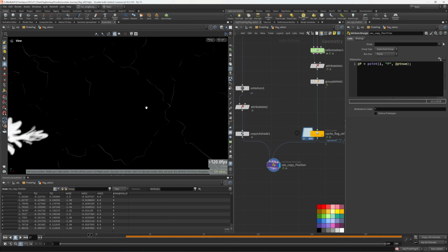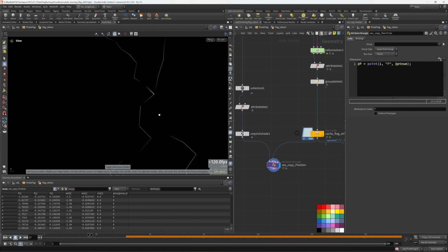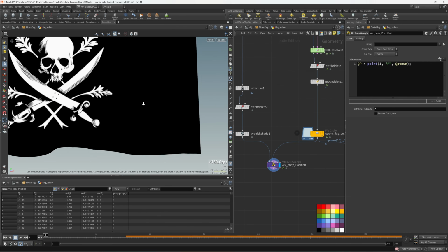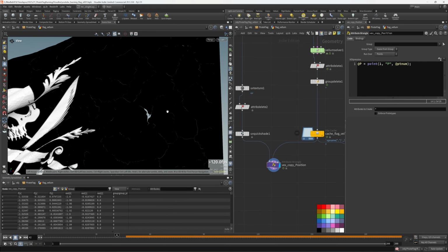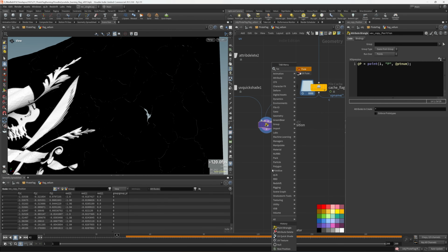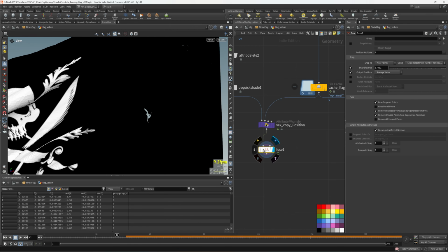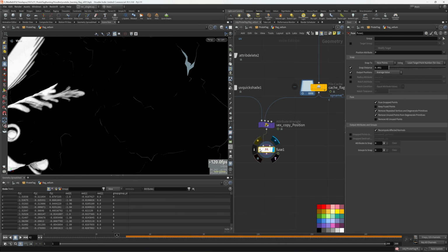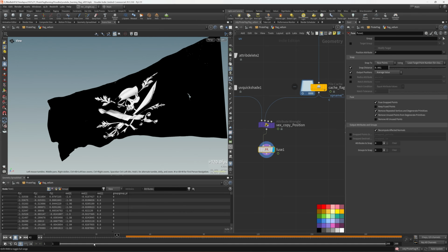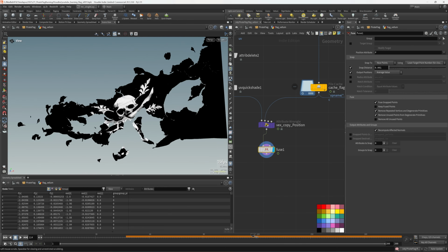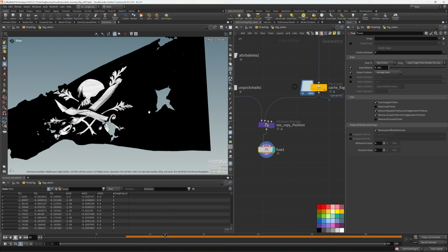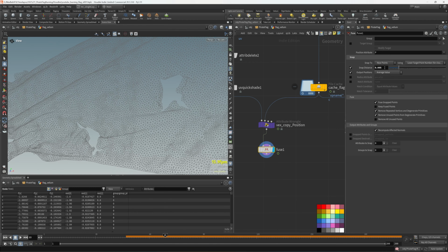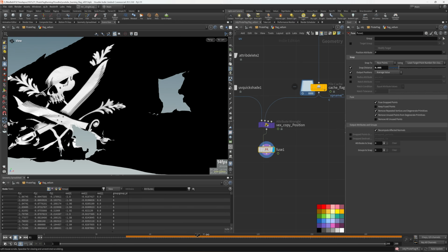We have seen here, just like the detaching before, actually detaching the piece, we can see a small gap here. We can solve that by doing a little fuzz, increasing a little value here. With the fuzz, we can weld the vertex here and solve the problem. Okay, actually we can increase the fuzz a little bit by 0.5.